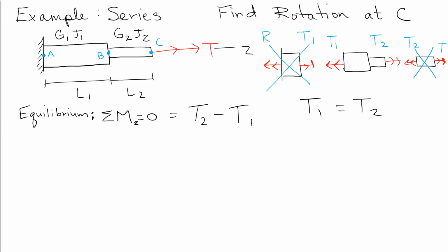I always have to relate things back to axial loading because to me that makes a lot more sense. If you think back to axial loading, these would both be positive values, right? Because they're both tension. But when I make my equilibrium statement, I'd have a negative sign in there. But then T1 will equal T2. They'll both be positive values.